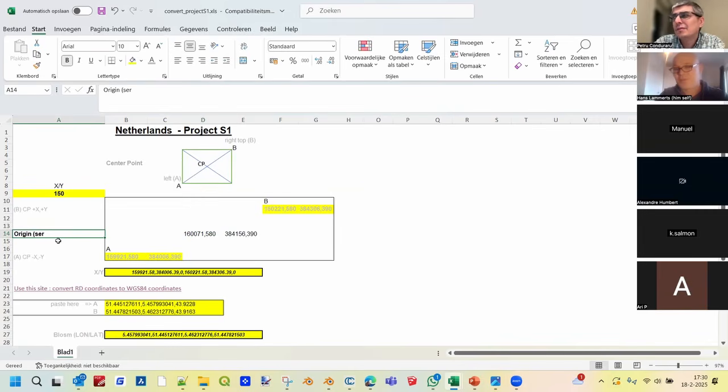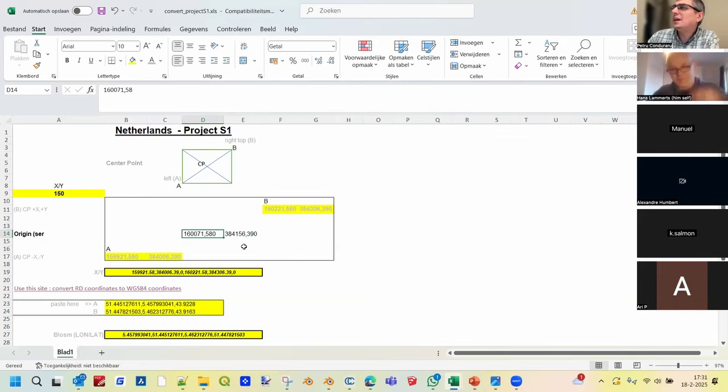But if you're working in a building environment and you don't do a lot of geospatial data, then you have to go to your surveyor and ask, I want to georeference my BIM base point, the 0 point of my BIM file. It needs to be located. Can you help me with that? Hans, these things that you call lat long, aren't these eastings and northings? It's the same, right?